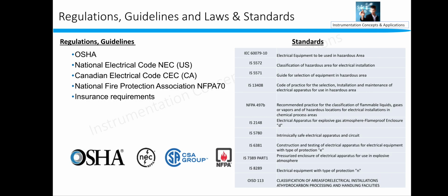And the standards I have mentioned on the right side, the main one and the mother of all the standards, is IEC 60079-10. This is for electrical equipment to be used in hazardous areas. And some Indian standards are also there, IS 5572 and 5571. These are a guide for selection of equipment in hazardous areas. They are followed in India.